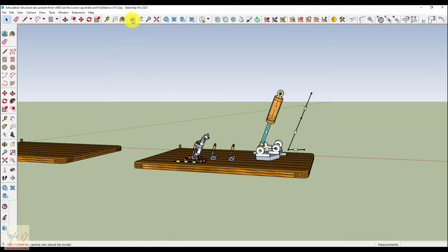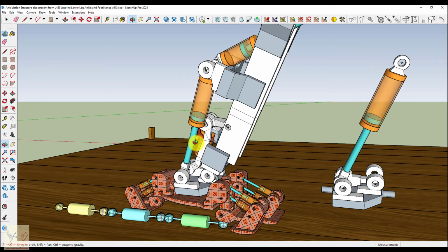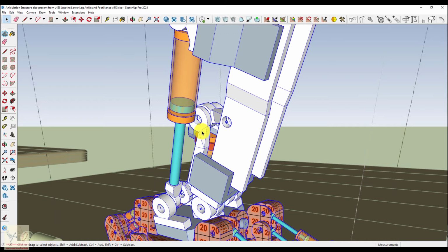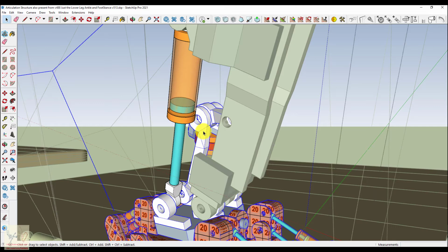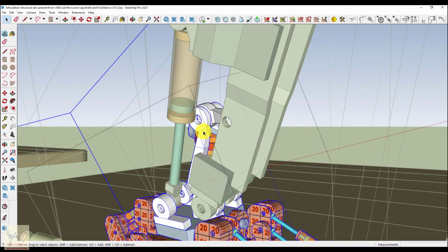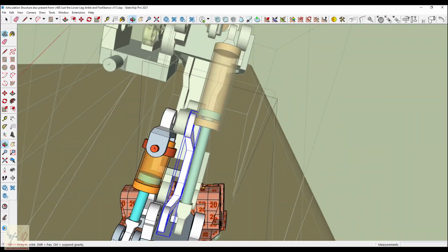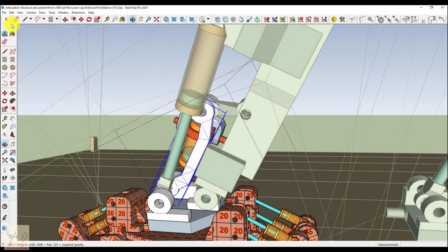Okay, and so inside of this, let's just pick something. Let's add a controller to this indexing arm. This is the indexing arm that allows inversion and eversion, the piston that controls inversion and eversion, to stay properly indexed, even though you added dorsiflexion and plantar flexion. So we'll copy that, and then we'll go back to number 71 here.